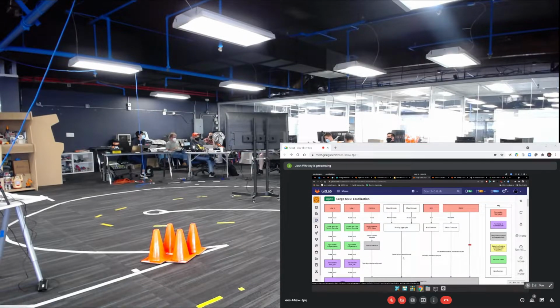So anyway, in order to help alleviate that, we are also now taking the GNSS data and using that for the initial guess for the NDT matcher, so that we have an estimate of where we're at to start with. And then we're also fusing that GNSS data with the output of the NDT matcher in an extended Kalman filter, which is our state estimator.